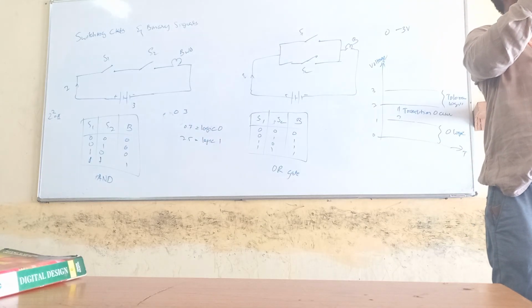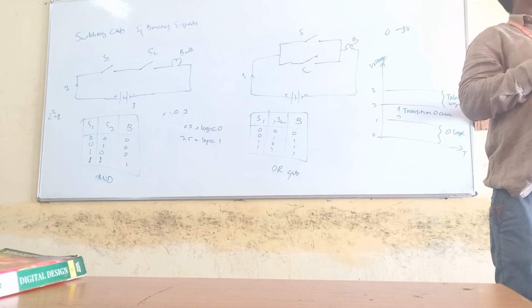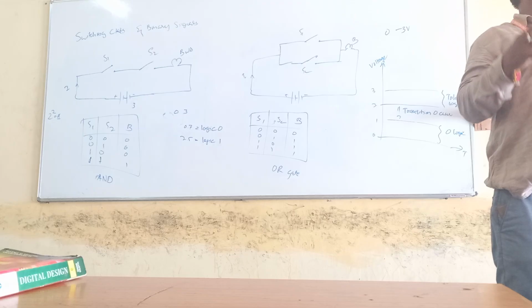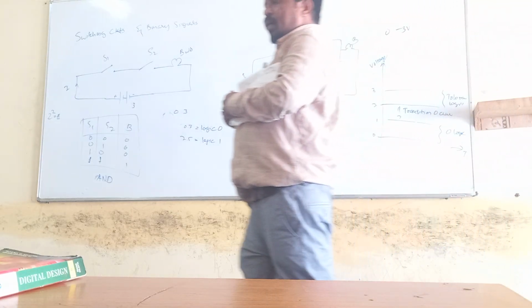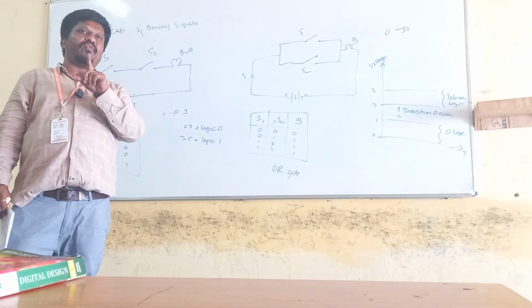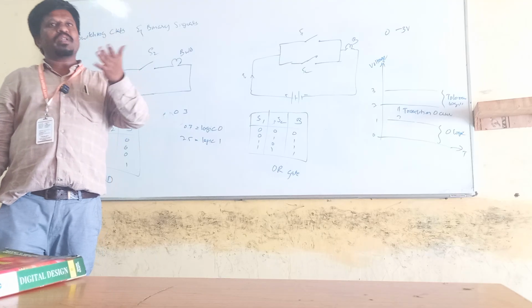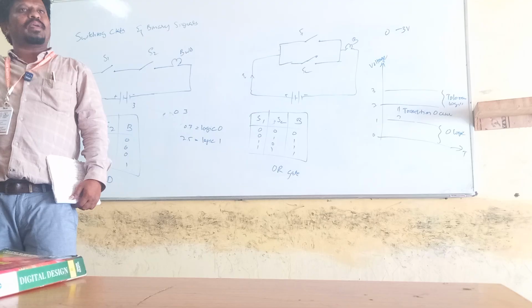But you will be using only a single line. For industrial purposes they use three lines, three-phase current. But for home appliances and home-related operations, they use only a single phase, at 110 volts. If I use more than 110 volts, definitely the MCB switch will trip.